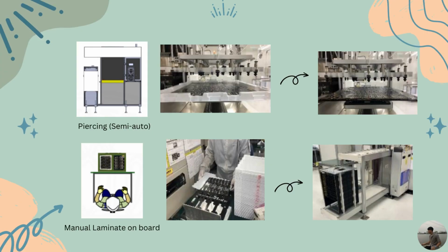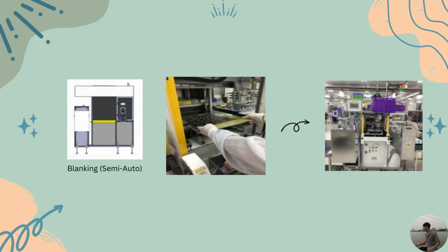The first and the second station, we added a slide rail at the output side and designed a new base for passing the product to the next station. This method is combining the similar work together. For the eighth station, we added the autoload and unload port to decrease the work time and let the worker in the previous station, which is 7, load the product into the machine.